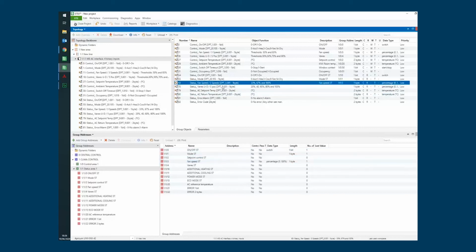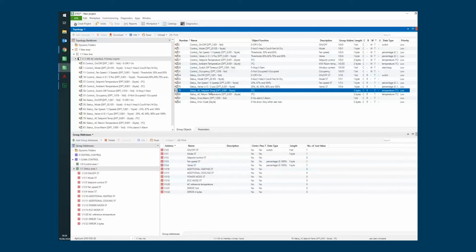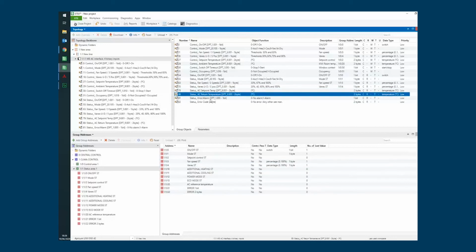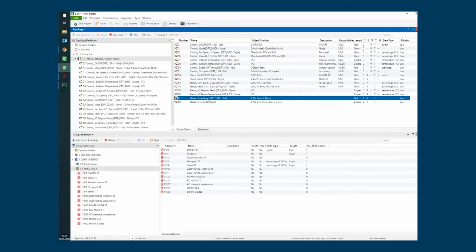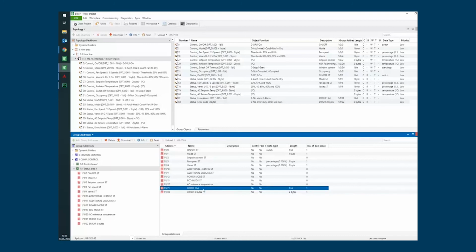Okay, this is the fan speed, the vanes. This is the AC set point temperature. This is the return. I will show you them later. This is if there is an alarm or not, if there is any error in the AC unit. This is the 2 bytes. Basically, this one will indicate if there is any issue with the air conditioning unit or with the communication with the AC unit and the interface. And this one will show if any air conditioning error. Basically, those errors should be checked with the AC guy.